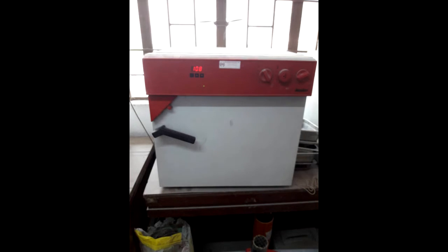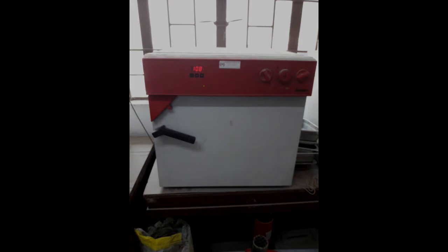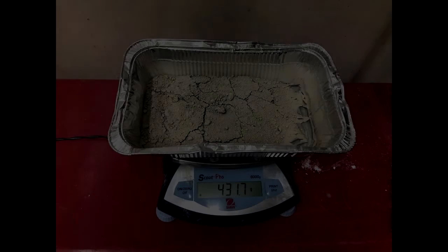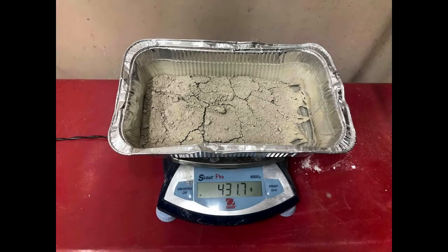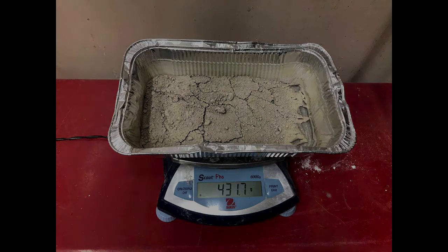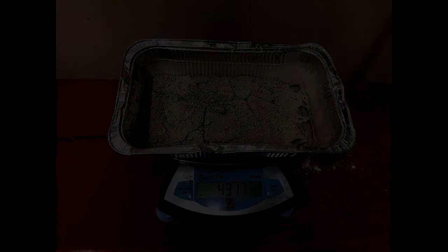The specific gravity is important to be within the acceptable range as it greatly affects the strength and compacting factors of the concrete mix. Absorption, which was calculated using the weight of the SSD and the oven dry condition, is also important as it affects the water requirements for a specific concrete mix to maintain a specific water-cement ratio. The applications of this experiment include mix design of concrete and the conversion of volume into weights and vice versa.